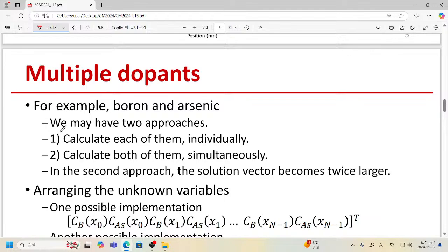For example, if you are working with just laboratory experiments, then you can prepare a quite clean wafer and introduce your impurity atoms by performing an ion implantation. After that, you heat the wafer up, then cut the wafer and take the same profile, then yes, you will have a certain beautiful graph.